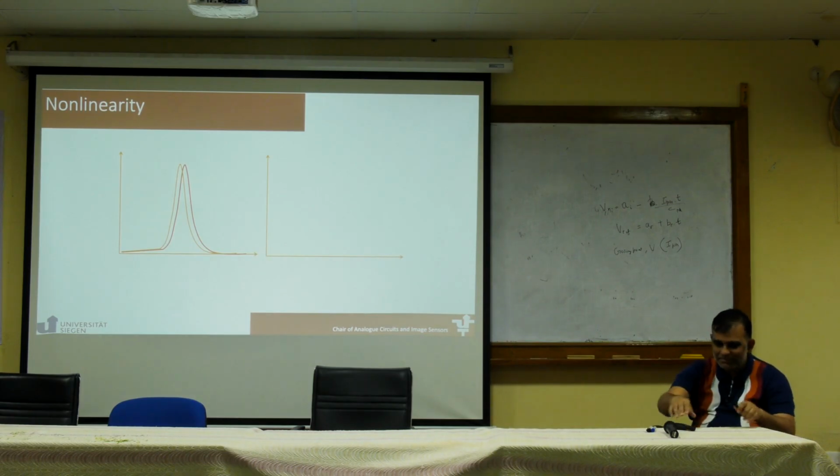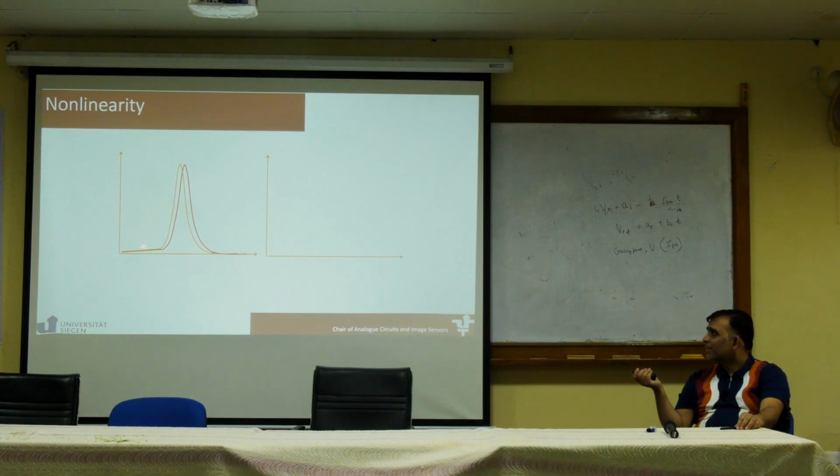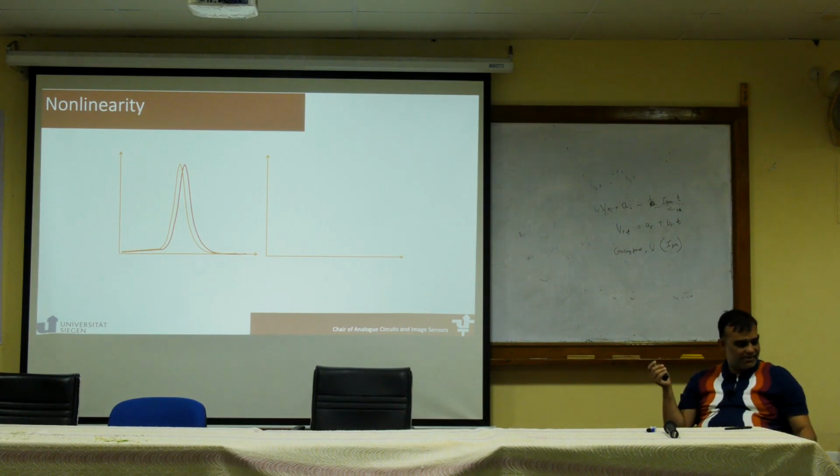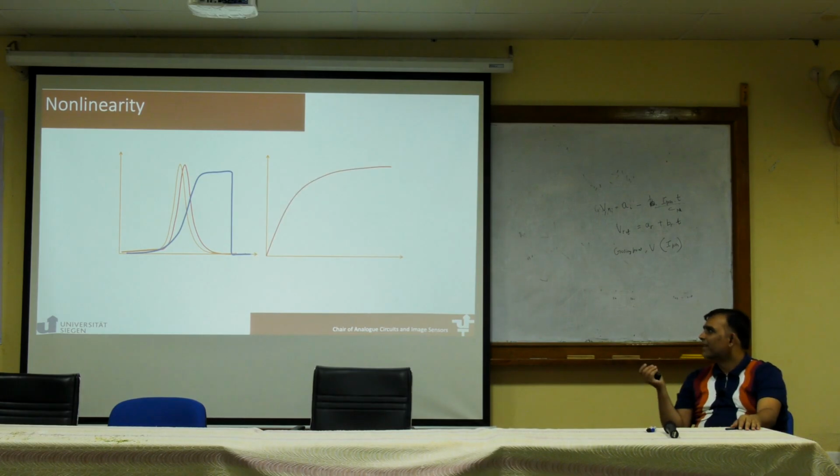So say that's a linear system wherein that was my original resonance frequency, something happened to the system, it moved. But the shift is still a very linear shift. It still looks like a resonant system. What if it starts looking like this? That's not a sinusoidal frequency response of a sinusoidal system. Or let's take a system like this. Ignore wherever this response comes from. If you ever see a response like this, what do you do? And you have seen a response like this in transistor responses. So how do we analyze this as electrical engineers?